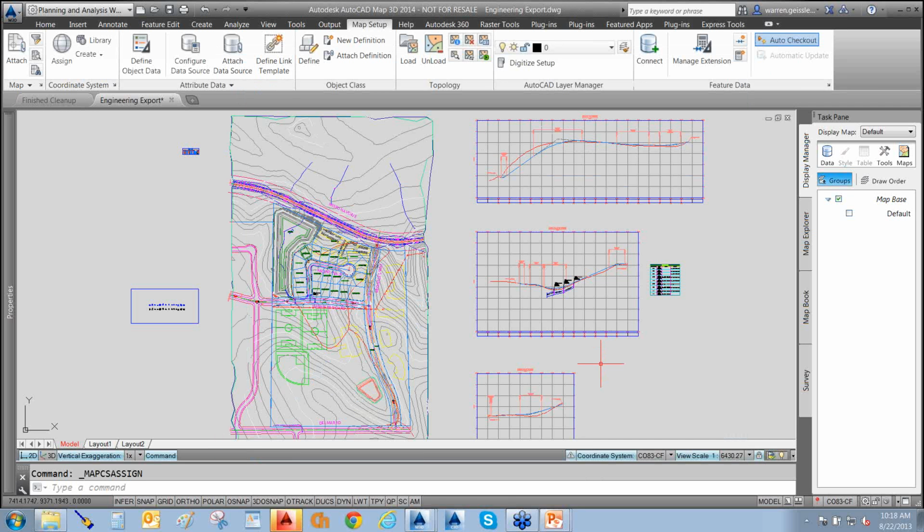Now, whoops, what if I didn't have a coordinate system? What if it was at 5,000, 5,000, 5,000? Well, you're going to need to pick everything up, move it to the appropriate locations, maybe do a little bit of rubber sheeting or some transforming just to make sure it gets into a coordinate system. But if this point is at 0, 0, or at 5,000, 5,000, okay, we're going to stop the webinar now and everything is going to go away. So step number 1, get that coordinate system going.